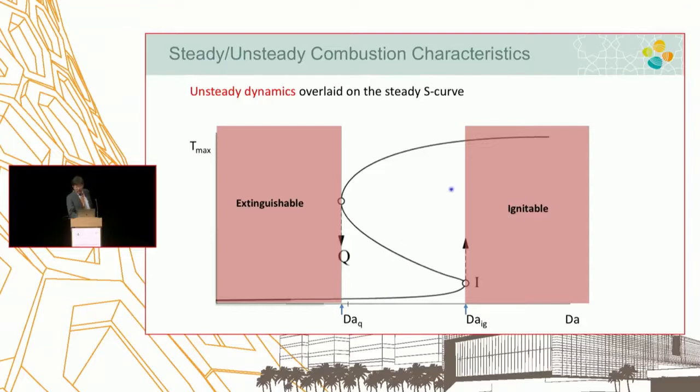And if you are talking about the ignition, extinction, and reignition phenomena, temporarily you have a local swing of the strain rate, or Damkohler number, to move the system out of this S-curve into this region. And then you have to bring it back to this in order to be able to reignite it. Otherwise, it'll be gone in full extinction.